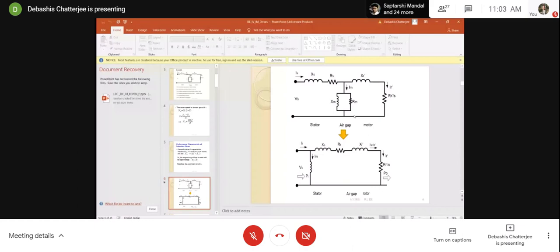And the total impedance will consist of two parallel paths and a series combination. So this and this will be in parallel and then in series with this. Ultimately, if you get the stator current, to find the rotor current you have to apply current divider rules and all, and then find the rotor current. So it becomes a little bit tedious. Okay, you can do it, and the calculation will be very accurate also.